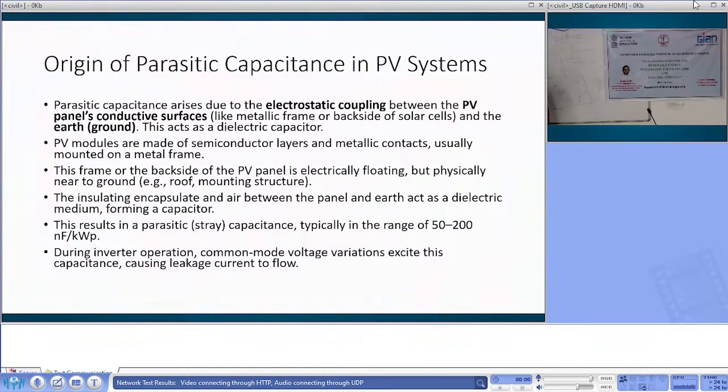That is already grounded. It is on the ground. Yes. Okay. Or we are providing a special ground wire also. You have the ground pit, and you are connecting it here. But the panel itself has got, it generates a capacitance. So there is a cell, solar cells are here. How many number of solar cells? So it forms the capacitance, okay, between the cell and the ground. Very interesting thing to know this.